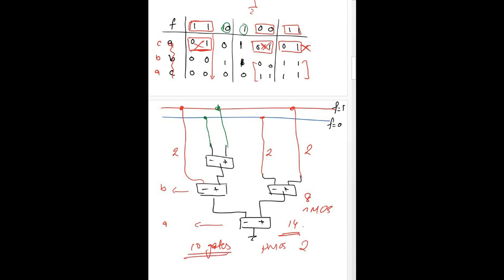So this is our design where we can use a dual rail network, and we can design our circuits in a simpler way. So we can say that the CVSL networks are easier to implement and easier to simplify. So this was our final discussion for these CVSL networks, and this is it for this session. I hope I will see you in the next session.